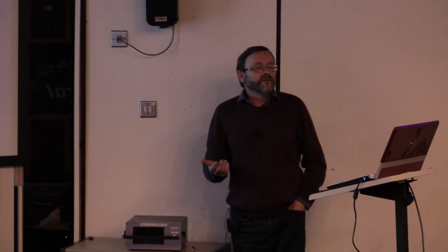But I think, you know, it's about patience. You just got to work out where the angles are. You've got to make sure your pole's vertical. You just got to take it step by step, make sure your frequency's right, your offsets are right, and you will get there.